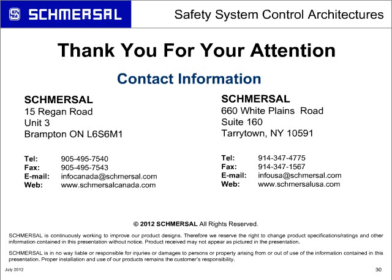But now, if an operator goes to door number 2 and opens it up, because door number 2 is wired in series with door number 1, you just cleared both signal paths, both safety paths, to the safety monitoring relay. So the safety monitoring relay sees both paths have been cleared and is reset and satisfied. I can restart the machine again. So that's what I mean by masking some of the faults. When you hit the second or third door switch, it can go undetected.